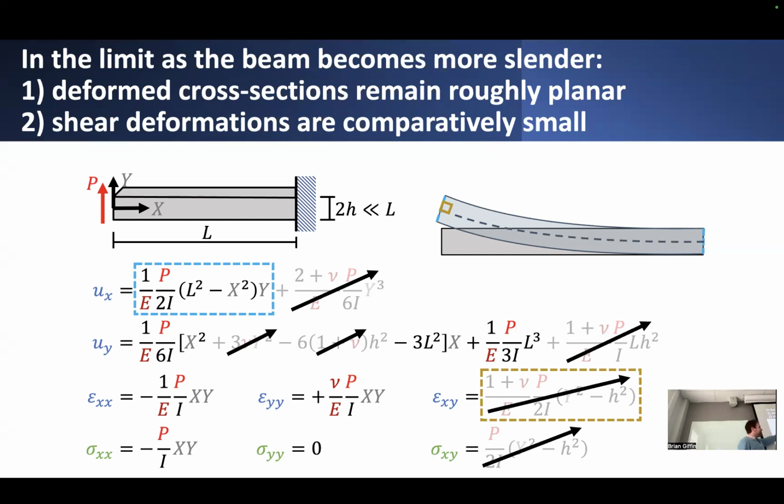So clearly, any terms that depend on h, as h becomes really, really small, those terms that depend on h are also going to become smaller and smaller, especially if they depend on things like not just h, but maybe h squared. So as you shrink the dimension of this beam smaller and smaller, you can safely neglect those terms or reasonably neglect their influence.